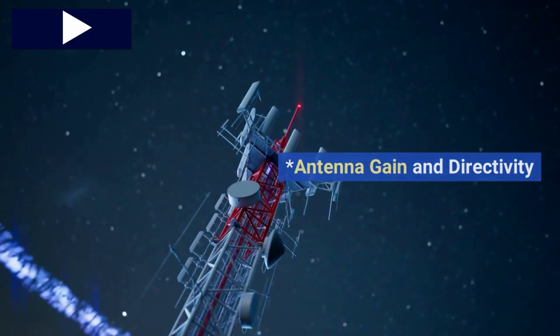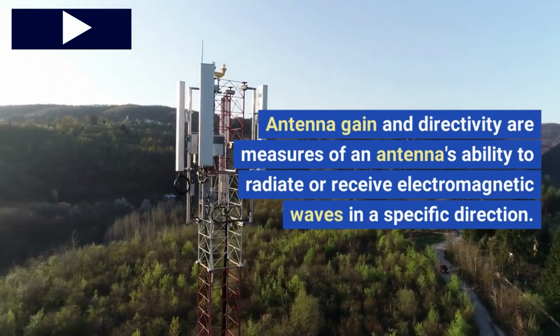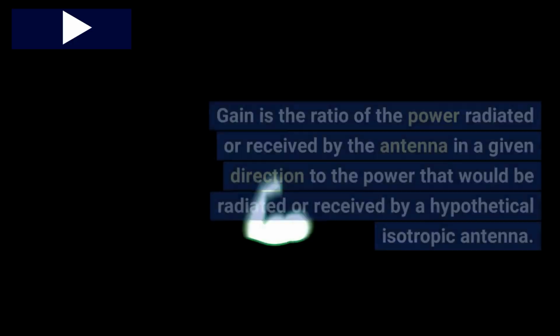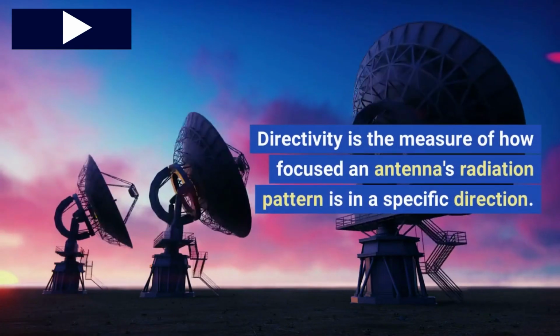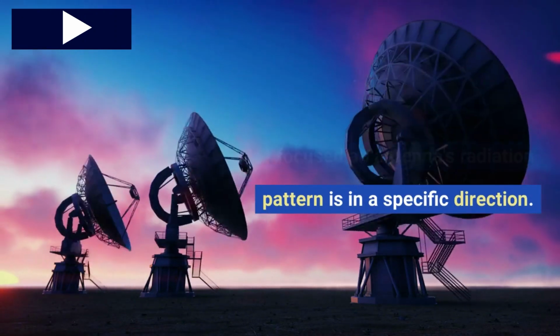Antenna gain and directivity. Antenna gain and directivity are measures of an antenna's ability to radiate or receive electromagnetic waves in a specific direction. Gain is the ratio of the power radiated or received by the antenna in a given direction to the power that would be radiated or received by a hypothetical isotropic antenna. Directivity is the measure of how focused an antenna's radiation pattern is in a specific direction.